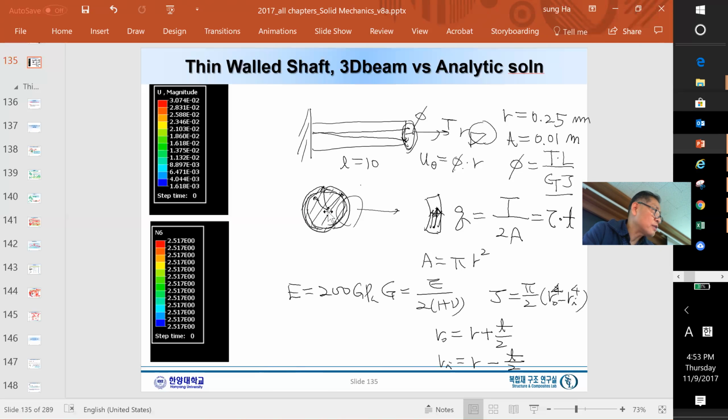So shear stress is the one we need to calculate. And at the last step, we need to know the shear yield strength, right? Man, so many things, huh? But every step is logical. This one is calculated from the yield strength. Yield strength of steel. What is the value?